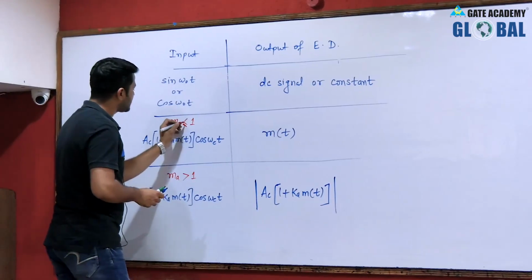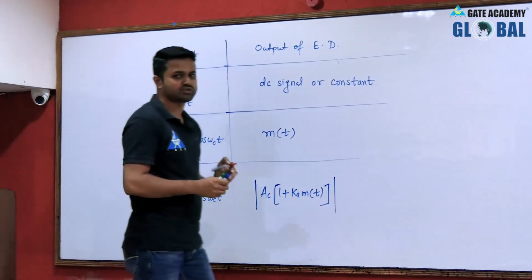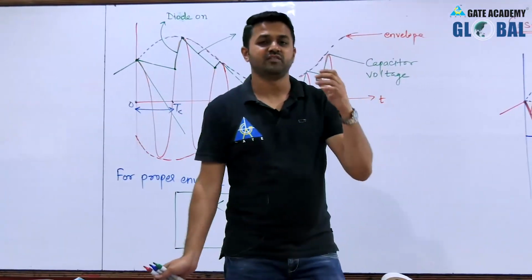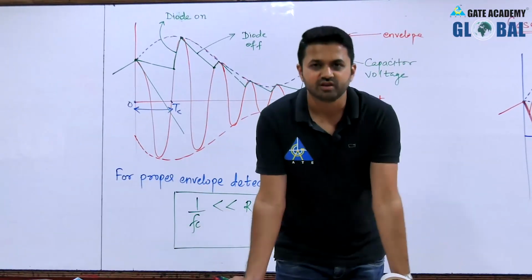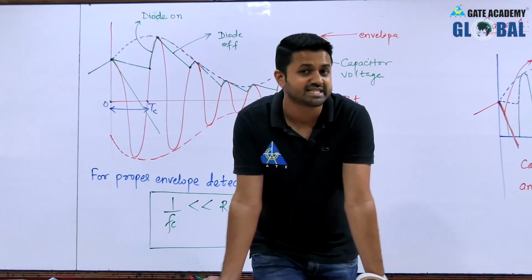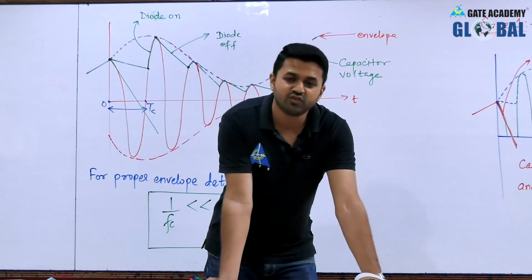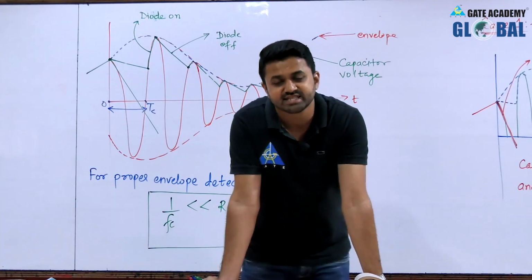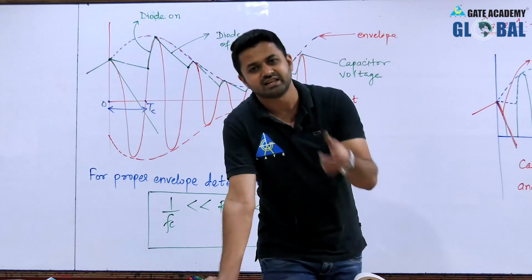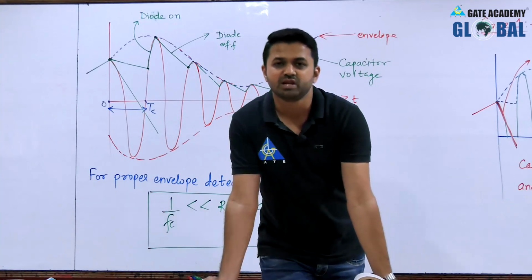We can make the modulation index equal to 1 also, and we will still get the original signal back, because our minimum envelope will not exceed 0. In case of over modulation, it exceeds 0 and goes into the negative side, so the information lying in that portion will be lost.